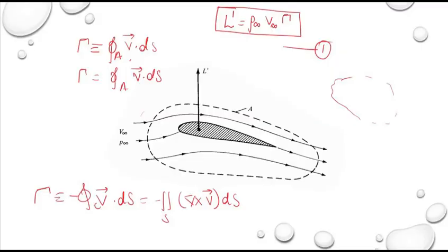and we choose a curve that is enclosing the origin, then the term in the brackets, that is curl of V, has an infinite value, while circulation has a finite value which is equal to the strength of the vortex. The same thing applies to the airfoil as well. If the curve is enclosing the origin, then circulation will have a finite value.